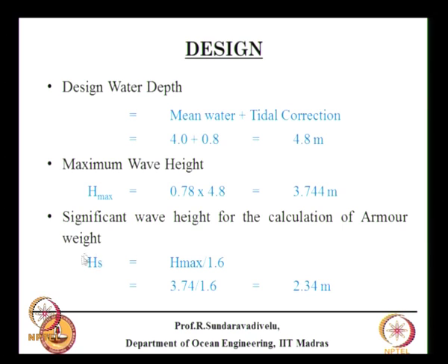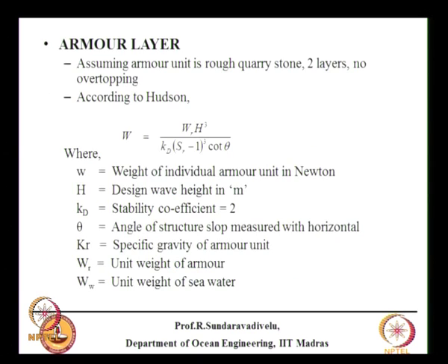See, the designing for significant wave height is like this: you have so many wave heights, we can either design for average wave height or maximum wave height, but instead we are designing for significant wave height, that is average of top 1/3 of the waves. But in ship design, floating body design, we design for H 1/10, which means the top 10% of the waves, that average we take. So it depends on how you do the experiment, present the result and derive the semi empirical formula.